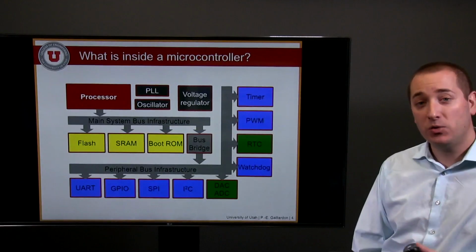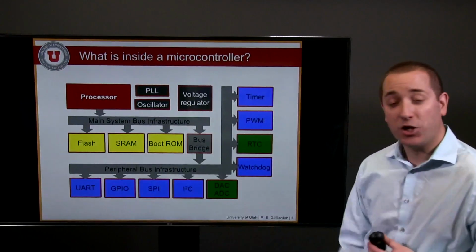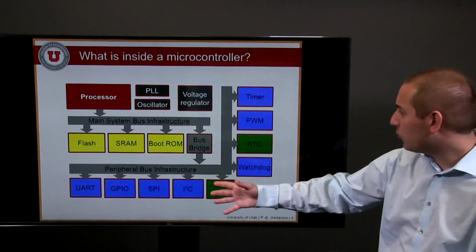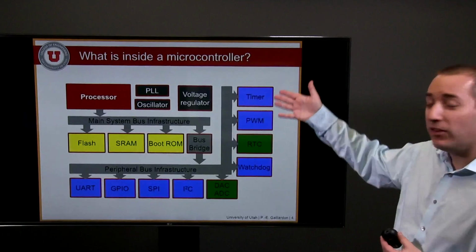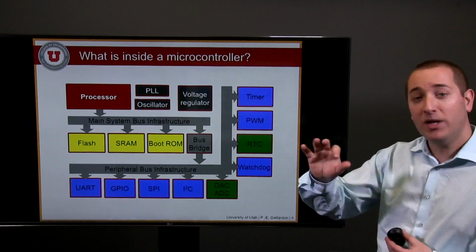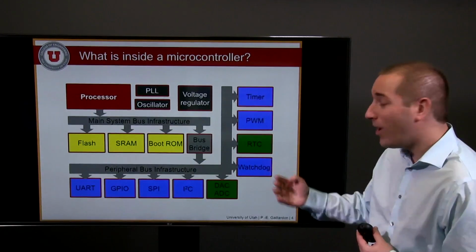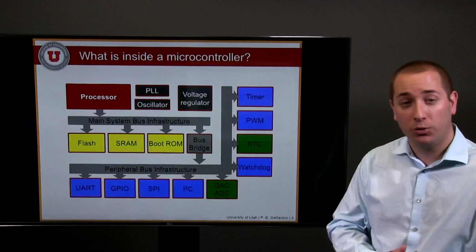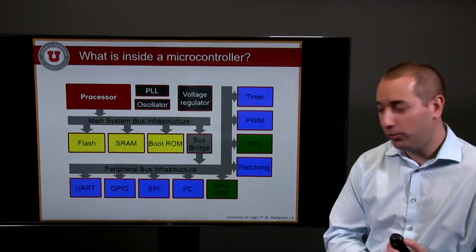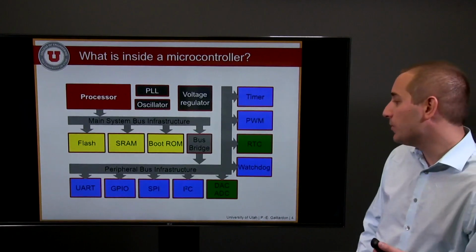And we can have a various set of functionalities: different communication interfaces, for example UART, GPIO, SPI, I2C, different time control units, timers, PWMs that are based on timers but are used to interconnect with the external world, watchdog timers that are used to monitor the correct operation of the system, as well as analog peripherals, analog interfaces, real-time clock, and so on and so forth.